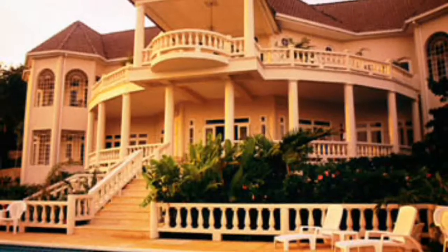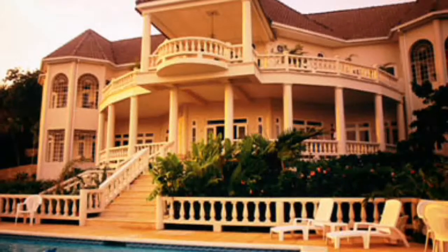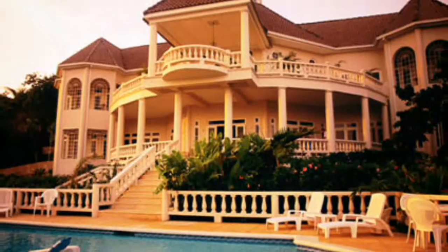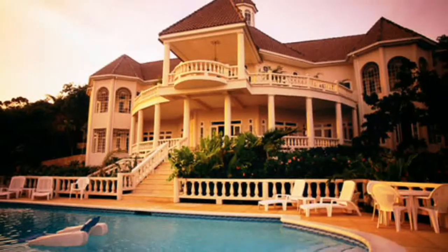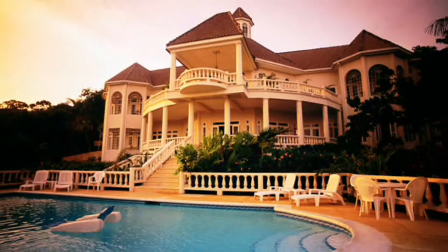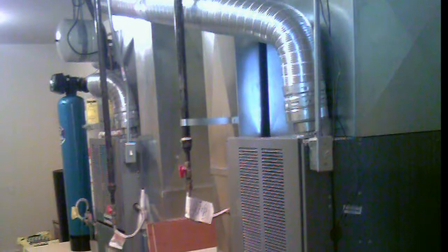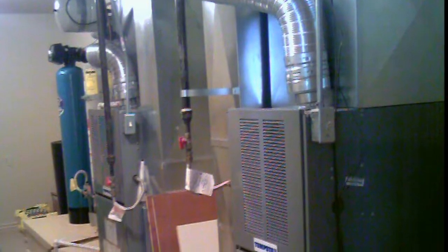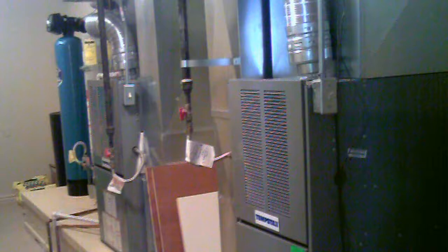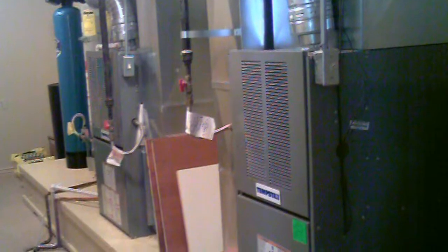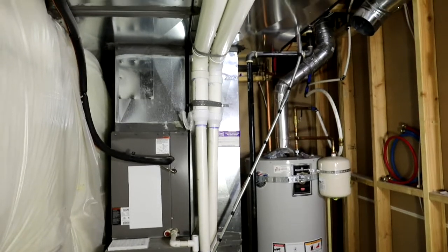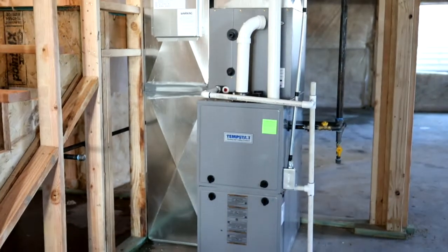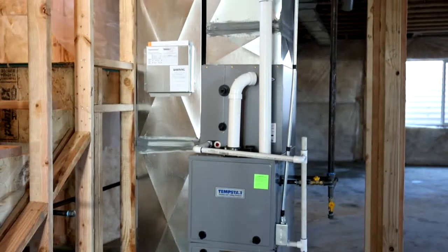Let's start by focusing on the number of zones for a home. For larger homes with multiple furnaces and AC units, zoning is automatically accomplished through the use of separate equipment for each area. Each furnace and AC has its own dedicated ductwork running to different areas of the home, thus allowing for differential heating and cooling. Such a system would also allow for simultaneous heating and cooling of different zones. Such a system usually needs to be built into the home at the time of construction.